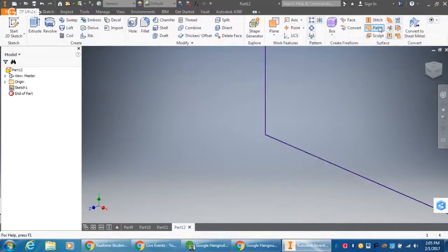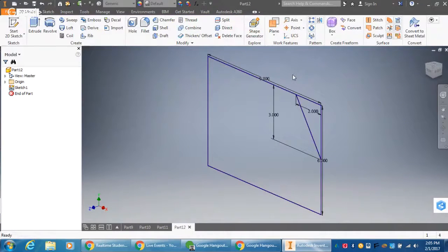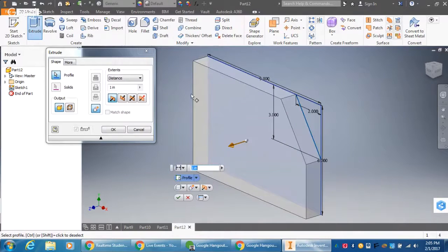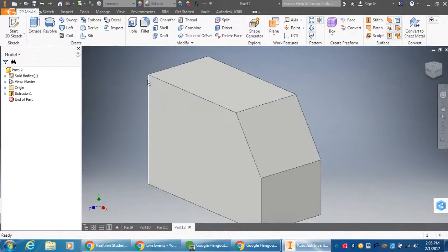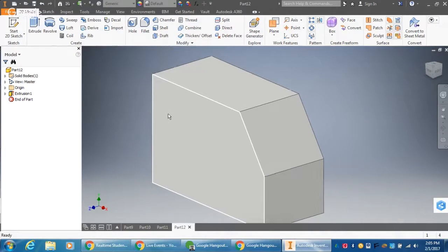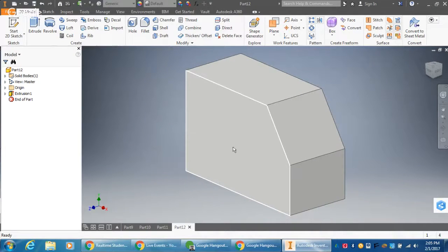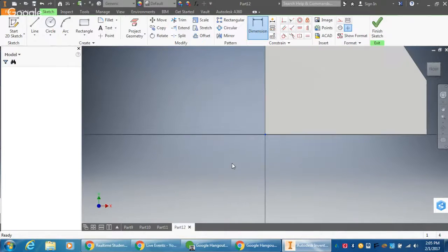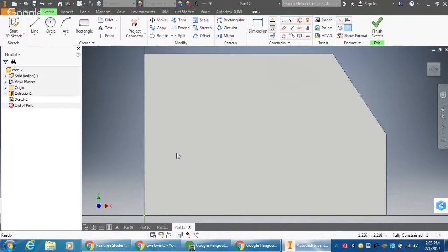I'm going to go here, finish sketch, home key, and I'm going to extrude that profile only, and that profile itself is going to be 4. So 4, enter. And there we go. And now I'm just going to cut off another chunk of this. Again, all subtractive modeling, right click, new sketch, home key.